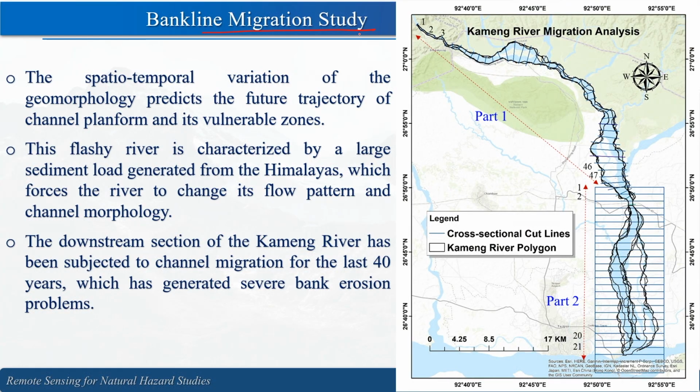Now, let us see the bank line migration study. The spatiotemporal variation of the geomorphology predicts the future trajectory of channel planform and its vulnerable zones, because this spatiotemporal variation, that is, over the time how this particular river is behaving, will help you to predict what will happen in the future, right.